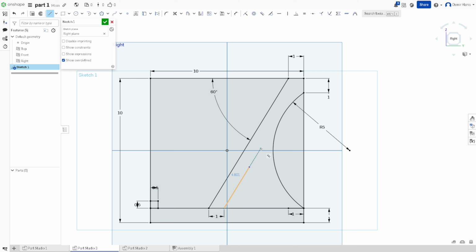Up, and maybe, I don't know, we're gonna check later. Again, we go to 3-point arc. We connect to this, and we can add whatever, but we can make this actually parallel to each other. So not that, but this, come on, this. Okay, we can't make it parallel because, okay, we are playing with ourselves. Let's go and say dimensioning and add this to be 5. Now it's gonna be parallel because both of the values are 5. So that means the curvature is basically the same. And perfect. We did this part.